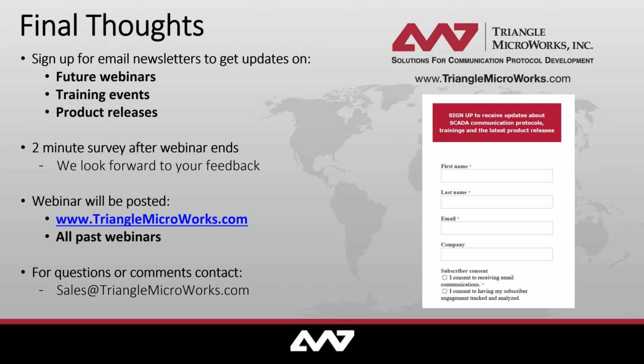But it's going to be that exchange between the different pieces of secondary equipment that's necessary for, let's say, general control functionality. Sample values, on the other hand, is going to be, I don't want to say strictly limited, because there are exceptions to the rule as always, but it's going to be currents and voltages that you're transmitting at very high speeds so that you can recreate that waveform on a subscribing device, which is typically going to be necessary for a protection algorithm.